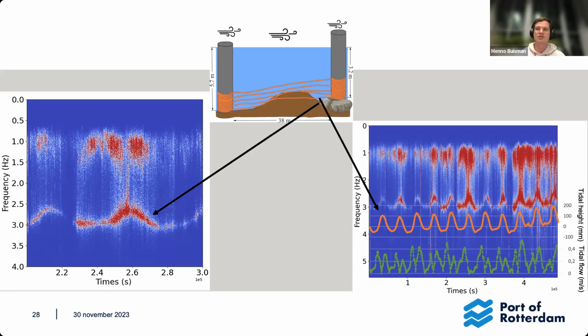Now, this can be related to the exposure of our poles to the water column, so that as it alternates, the frequency at which it resonates because of the flow starts to change. But it's something that might be interesting to think about, that the relationship between the vortex-induced vibrations and the flow might be more complex than at least we initially thought.